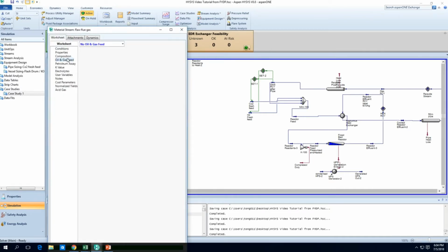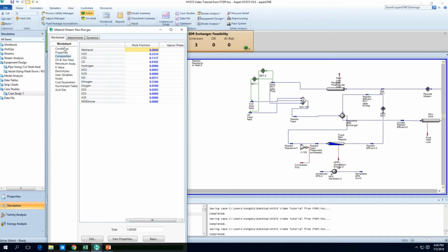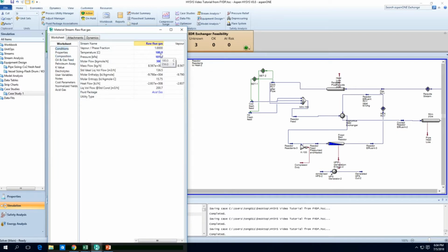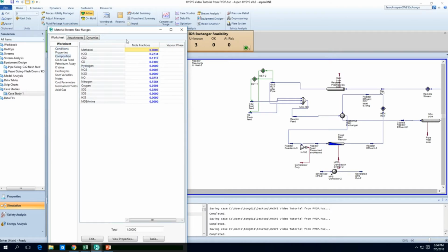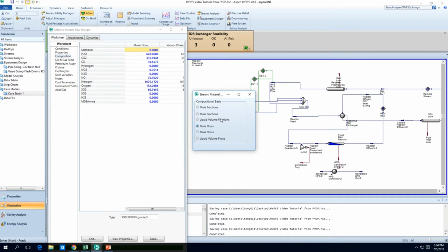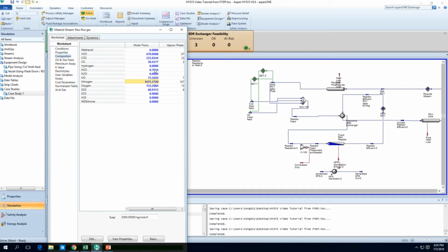And yeah, so what do you need to deal with first? Well, the temperature is pretty high, and that's a good thing because we can use that kind of heat. The pressure is a bit low, meaning to say we'll need to compress it so that we can force it through our absorption tower. So in this case, yes, we are using amines to extract this CO2 out. So we have our flue gas and we're just using amines to get our CO2 out.